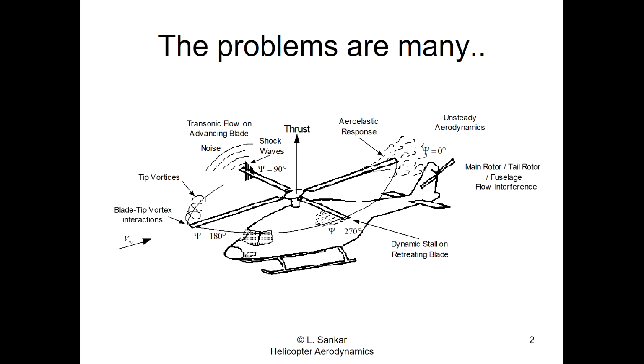But most of the time, the rotor itself will produce not only the lift to hold up the vehicle, not only the propulsive force to push it forward, but also all the forces and moments needed to roll the vehicle to the left, to roll the vehicle to the right, and so forth. You use the tail rotor thrust to control the yaw to the left or the right.